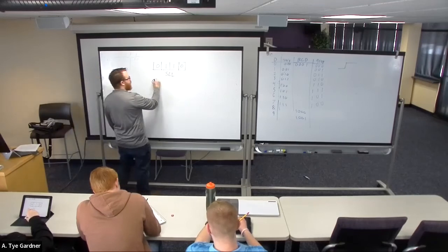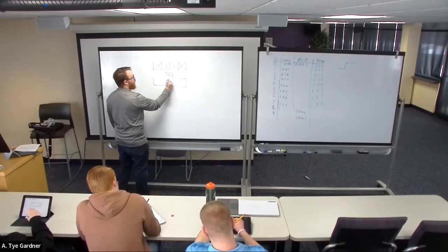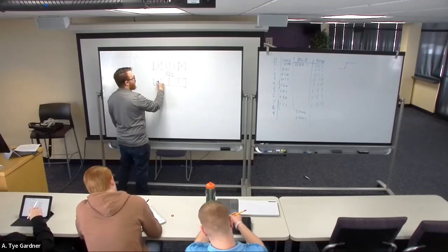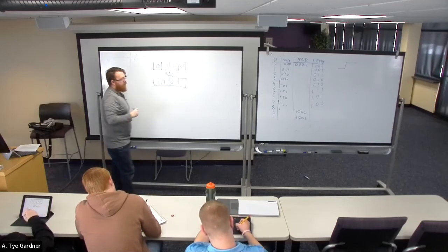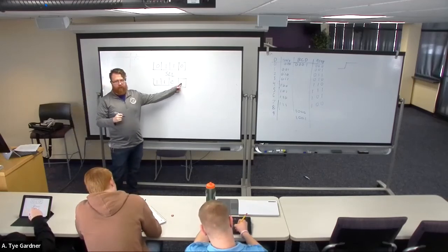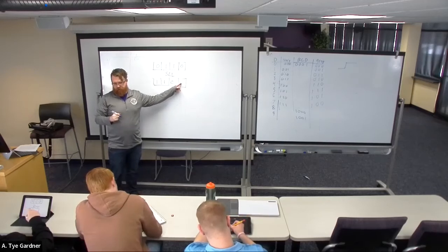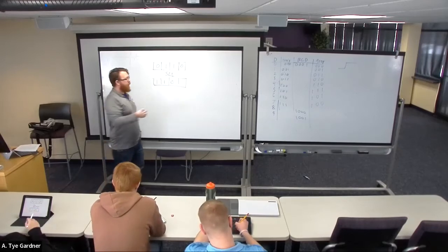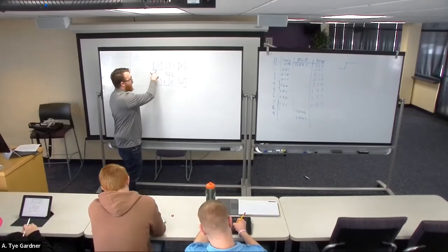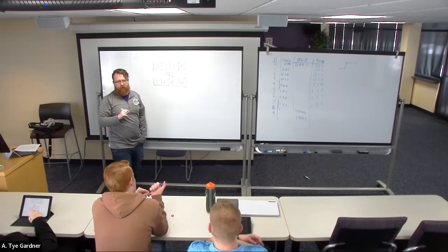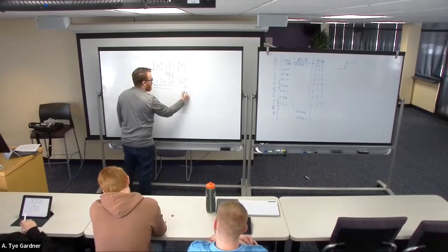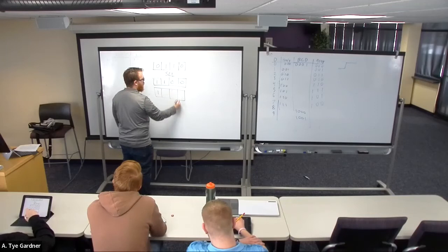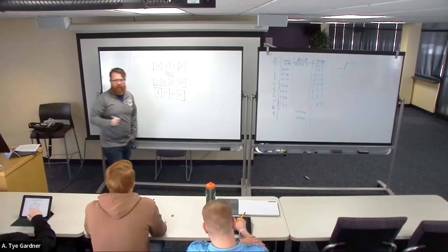The SLL would transform it, well, it shifts to 1 1 0. Then the question is, what happens here? And we can actually get to choose. We can design whatever is easiest. Shifting in zeros is very common. It's not this 0, it's just a 0. So if I kept shifting again, I would get that. The 1 goes away.